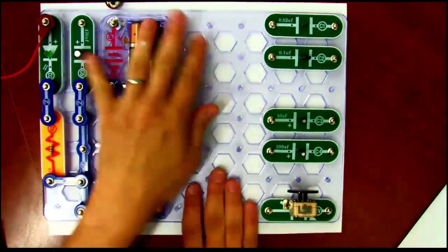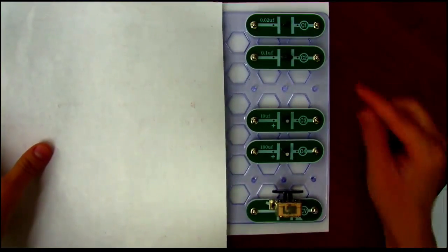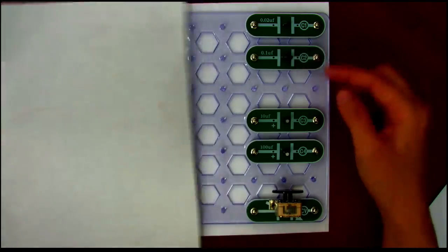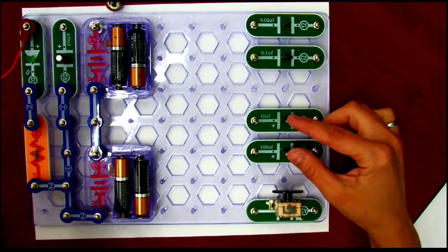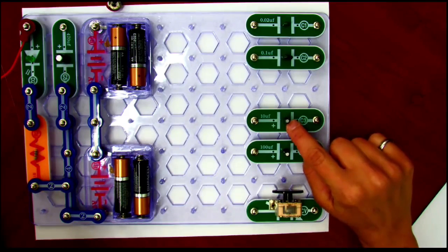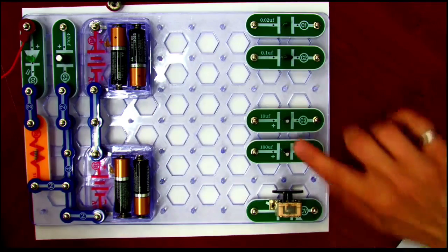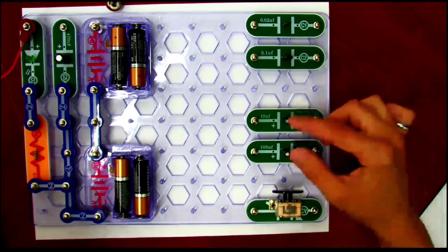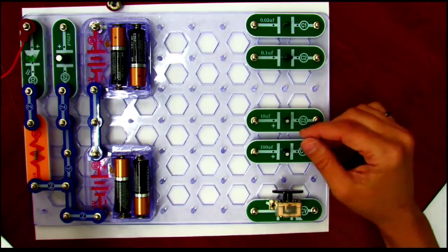So first we'll start on this side. Cover up the side over here. These are some different capacitors. These 2 are ceramic based. And then these 2 down here, and the one I'm going to use in the demo, are electrolytic capacitors. The design of them and the fluid that's in them allows you to get larger capacitance in a smaller area, so you can get 10 microfarads, 100 microfarads in that little volume. You've probably seen these in different devices, just how they're designed.